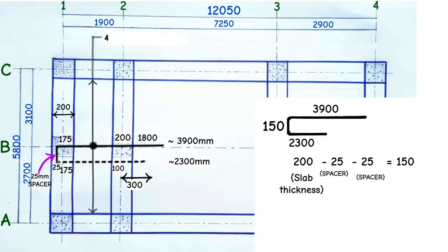These are 40 steel bars that we need to cover a distance from grid line A to grid line C of H12. H12 is the type of mark or steel bar thickness. The bar mark as 01. The bar mark shows us where steel bars start and end from in a structured drawing. Each steel bar shape has its own bar mark that differentiates it from the rest, and then at a spacing of 150mm center to center from one steel bar to another for bottom 2 and top 1.